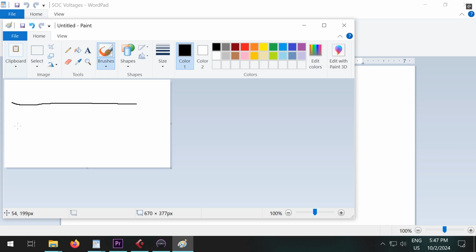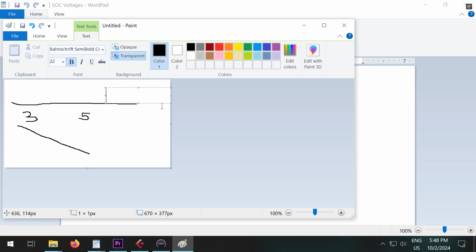What you don't really want is this, as it approaches higher frequency. Let's say you want to reach 5 gigahertz here, and this is, I don't know, something small like 3. As you approach it, you get a lot of V-droop. That's basically what most of the V-droop is. Once you approach the higher frequencies, to reduce the load on the CPU in terms of voltage, you'll begin to V-droop. The famous voltage droop. Droop is like a flop, so it begins to flop. When you keep it straight, that's more of a flat curve, and on ASRock, this is level 1.